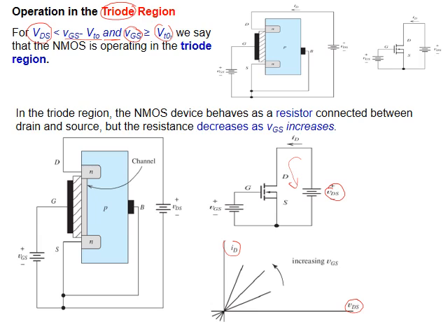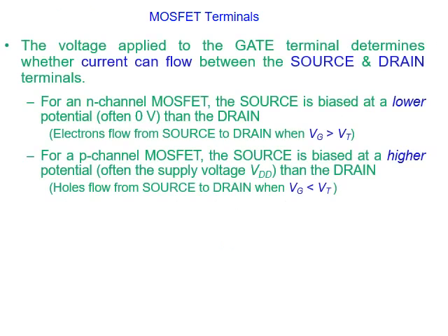Now, when we increase VGS, what will happen to the resistance? I mean, the transistor as a resistance. It is reduced. When it is reduced, the current will increase. So you see the line increase, and up and up. You got it? Now this region is where the field effect transistor works as a variable resistance, as an amplifier. While in BJT, it was working in the active region.